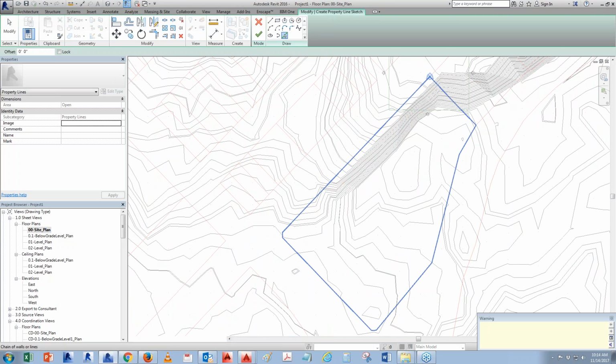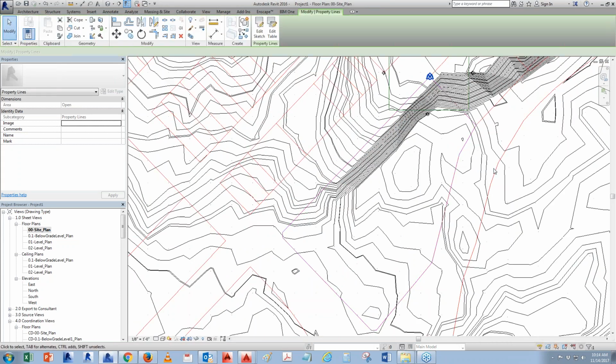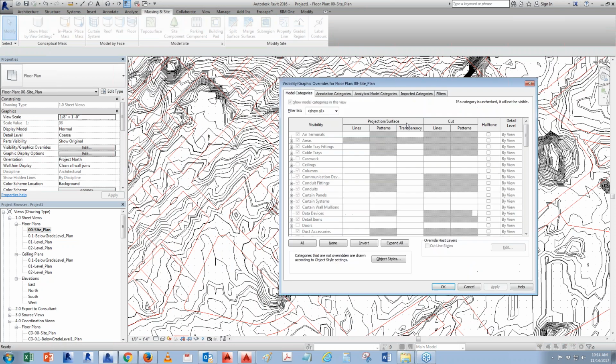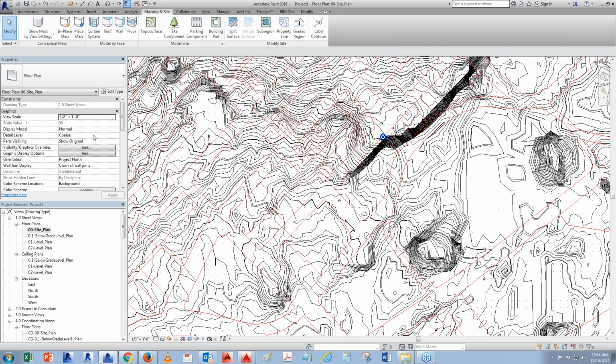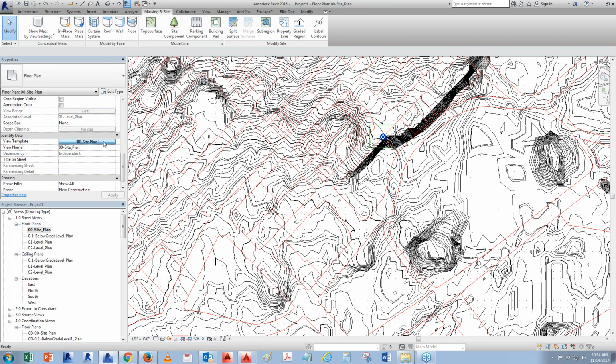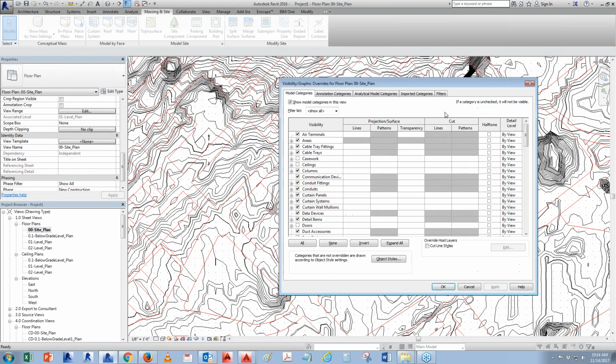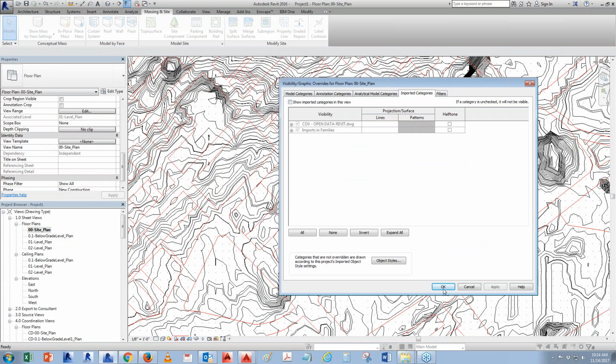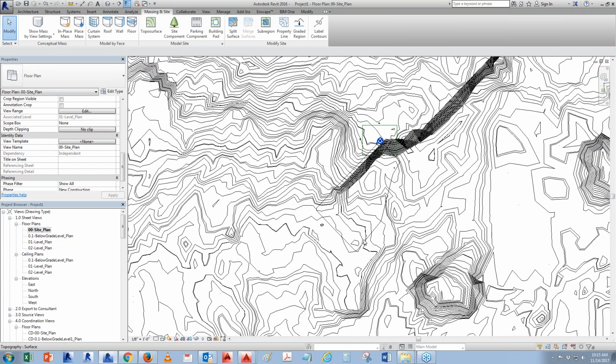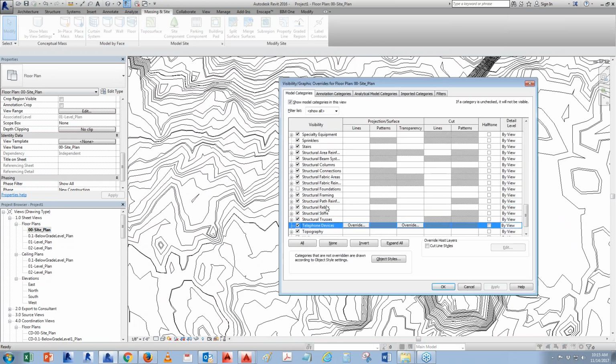Okay. So what I'm going to do is I'm just going to choose that. The boundary is never going to be accurate. That's fine. And then say OK. What you can do now is say, okay, well, first I'm going to turn off the filter. Just say none. Go to filter and check it off. And now you have a property line with your topo on it.